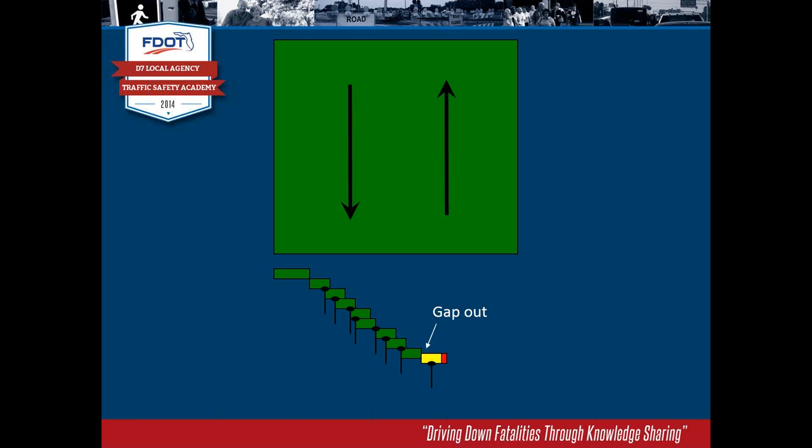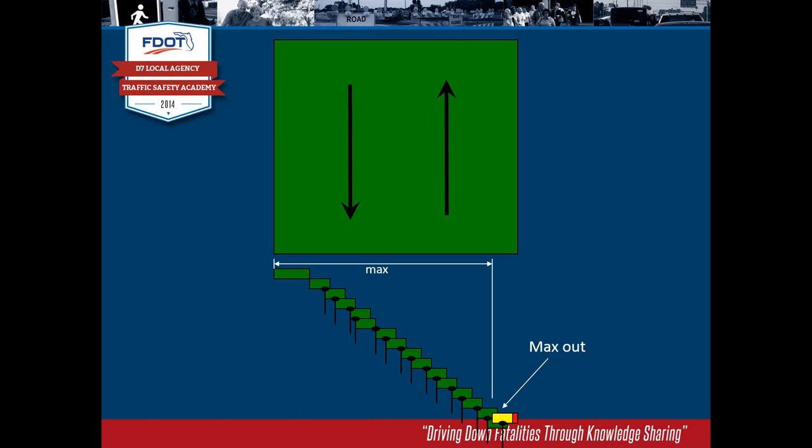Now the other way that you end an actuated phase is what's called a max out. One of the parameters we talked about you put in is what's called the maximum. And what you see on the screen now, it's extended, extended, extended, extended, extended, and there's still lots of vehicles coming. But you've given the controller for each phase what the maximum amount of green time is.